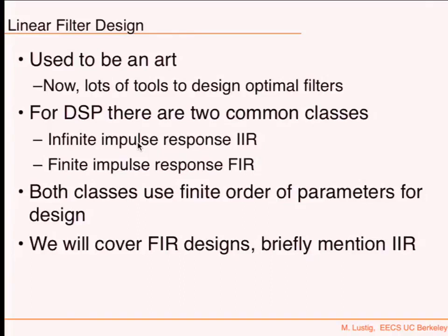What we will cover for this class is mostly FIR design, and I'll briefly talk about IIRs. The reason for this is because these are quite useful. There are excellent tools that allow you to design them. In most cases, people use IIRs because they have less computational complexity, but computational complexity today is not as much of an issue as it used to be.